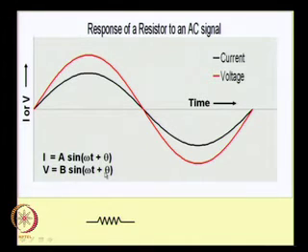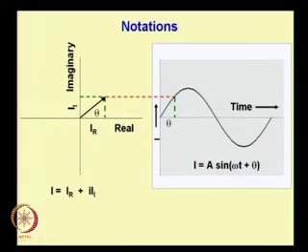Now there is another way in which we can represent this data, which is more convenient to manipulate and is what is typically used in conductivity measurements, impedance measurements, and electronics. We can represent the same sine wave using a vector, where theta represents the angle that it makes with this horizontal axis. This vector can rotate about the origin with the same angular frequency omega that is associated with the sine wave. Depending on where it is, for example at this location, it represents this point on the sine curve.